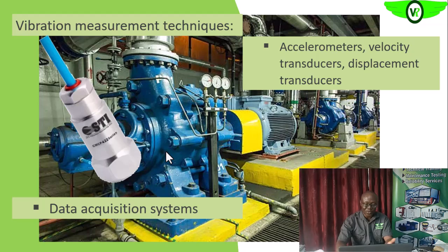So with this, you go out to carry out your vibration measurements. Remember, on each bearing housing, you have the vertical, the horizontal, and the axial direction, as we discussed earlier. On the motor too, the inboard end and the outboard end, you have those orientations, those axes to collect vibration